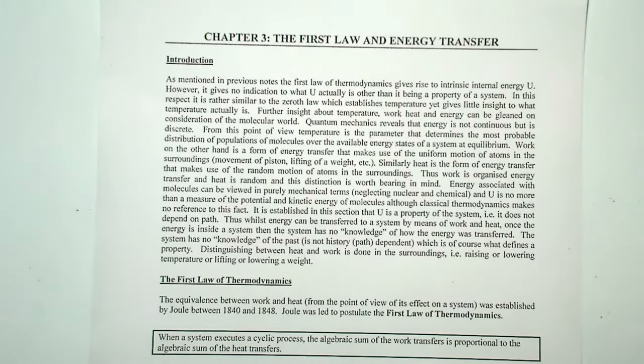Now, we're going to see the mathematical representation of that in a moment, but as far as whether it's a property or not, and I know I've mentioned that a few times, the internal energy is path independent. What I mean by path independent is when you think about the PV diagram, for example, the state diagram, it doesn't really matter what path you've taken. There's a certain value of U, and that is a property.